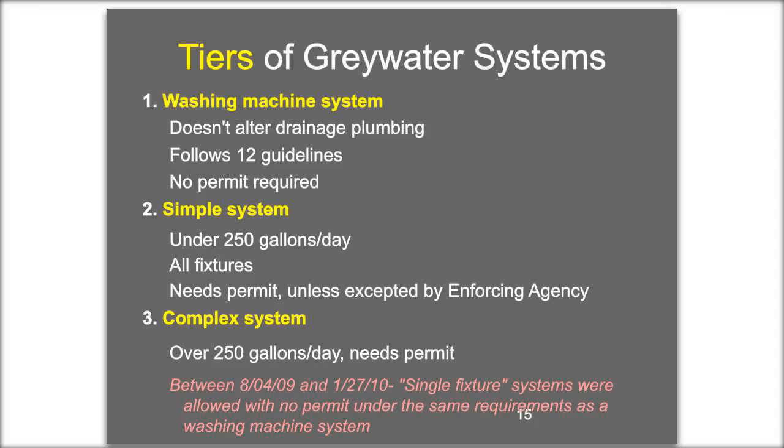And there's a question about the 2-inch cover on the outlet. So the outlet is where the graywater is leaving the pipe or the tubing and coming out into the environment, so that's where it's irrigating. And there has to be a 2-inch cover over it. It's usually a valve box, some kind of way to cover it up. If it's in drip tubing, it might just be covered by 2 inches of mulch. So however the water's coming out, it needs to be covered by 2 inches of something.